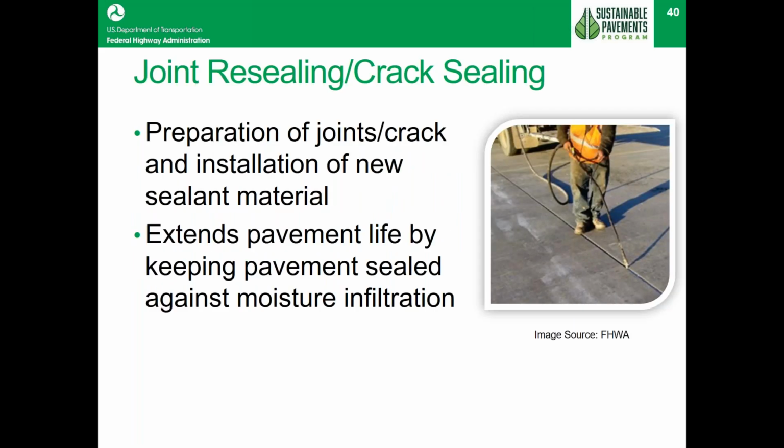So first off, we're talking again about joint sealing and crack sealing in concrete. This is usually a pretty easy thing to do. It's maybe more important in concrete than it is in asphalt because concrete slabs tend to expand and contract more. The goal of all the sealing is to keep the water out, because the water in the subgrade does a lot of damage and shortens the life of it.